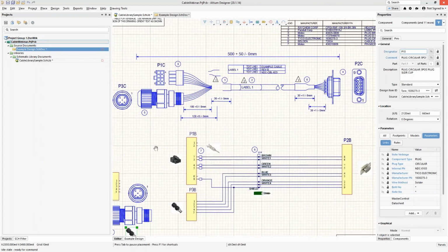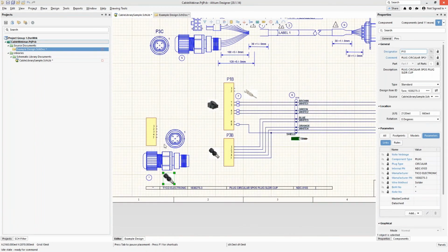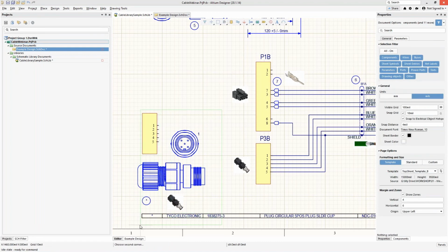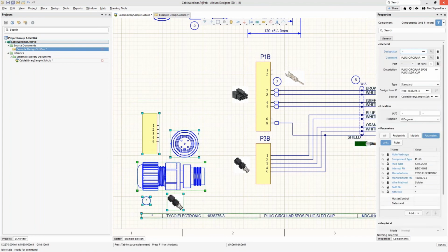So I have these here, and before I scatter them off to the different corners and locations, there are things I want to get all on the same page. For example, if I click here, you'll notice that this says P question mark. Now notice how I did this. I'm not going to select left to right, I'm going to select right to left because I want anything that it touches to be included. So I'm going to click in this and call this P10. Now all of these will be P10, okay?